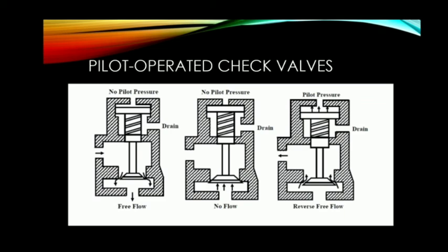The check valve poppet has the pilot piston attached to the poppet stem. A light spring holds the poppet seated in a no-flow condition by pushing against the pilot piston. A separate drain port is provided to prevent oil from creating a pressure buildup on the underside of the piston. Reverse flow can occur only when a pressure that can overcome the pressure in the outlet chamber is applied.